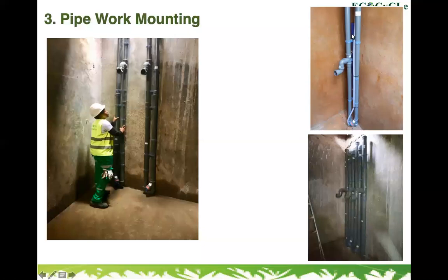Now, those are the mounted pipes. You can see this one, the one on the far right, at the upper side, that's for the filling for a small system, the ones that bring all the sewage to the treatment water tank, and that's the elbow. The one on the lower side, that's also for the clear water discharge. And these ones are for a bigger system. That's why you're seeing them. There's very many. It depends again on the volume that is being discharged. The bigger the system, the more airlift pipes you have. Okay, next slide.